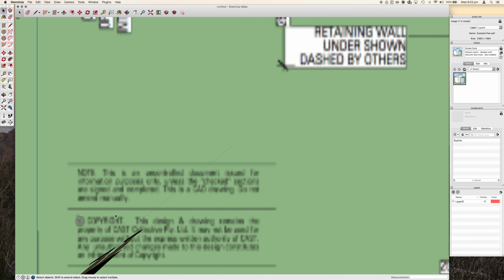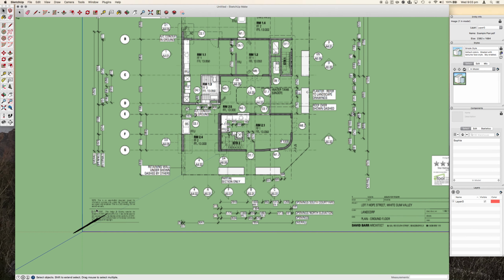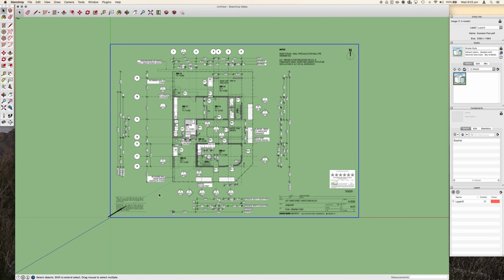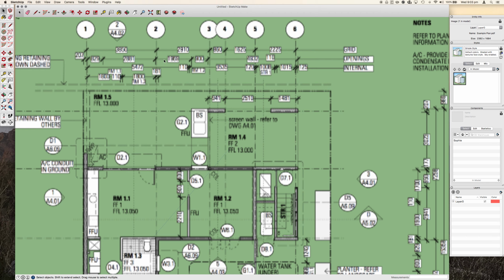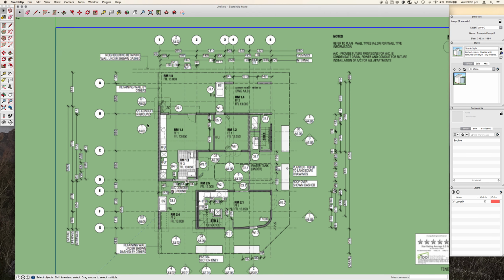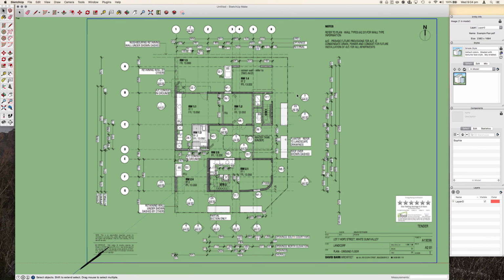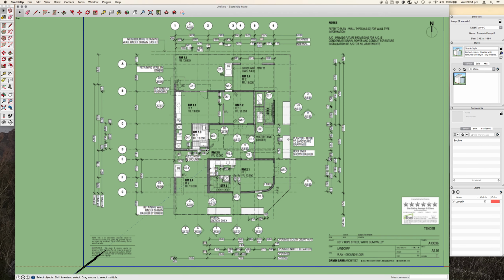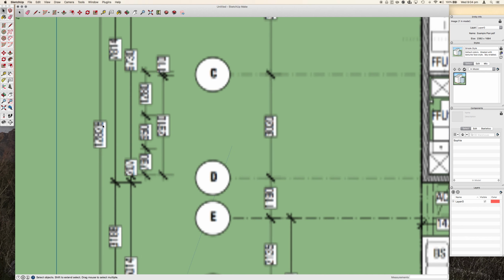So some of the things aren't going to be legible, and that can cause issues if you can't actually read one of these dimensions to scale the plan. You might actually have to have the plan up on a different screen to initially scale it. And it's by no means millimeter accurate, but it's accurate enough to derive your initial takeoff in lieu of other information.